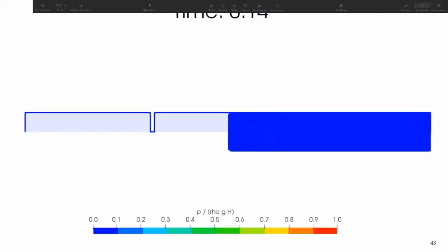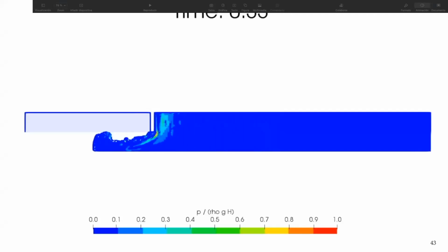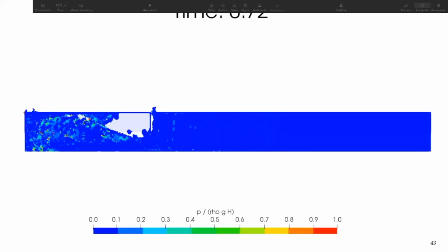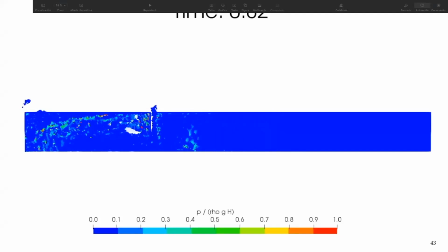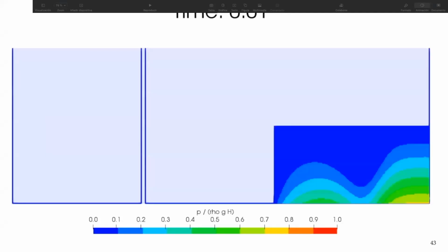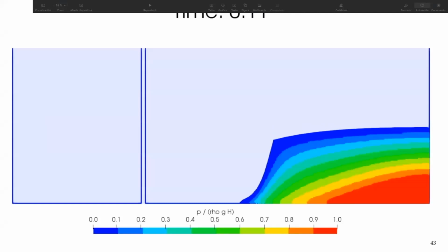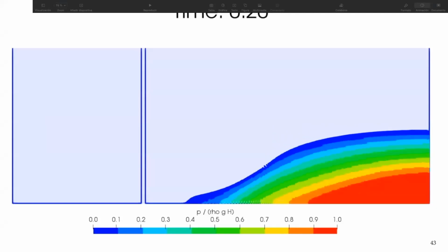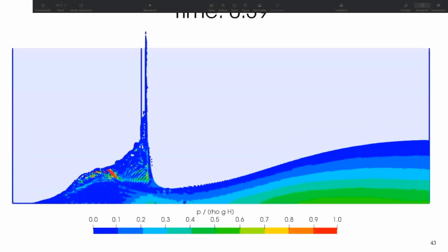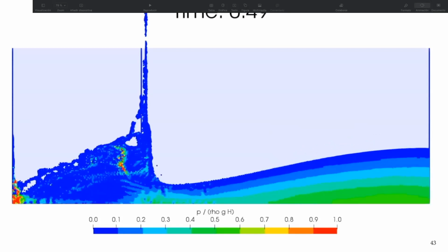So in this research, we have computed the value of this potential for all the well-known kernels and also the cubic spline as well as the Gaussian kernel. The Delta SPH scheme is used in this case, as well as a predictor corrector method. Now you will see in the next experiment, these videos correspond to the Wendland kernel C4. You can see that the pressure field, now in the next video, presents certain instabilities that I believe are certainly related to what we have seen this morning in the presentation of Professor Mateo. But the hydrostatic structure is, in any case, well conserved.